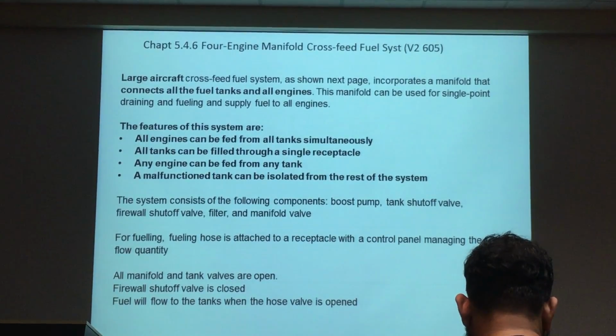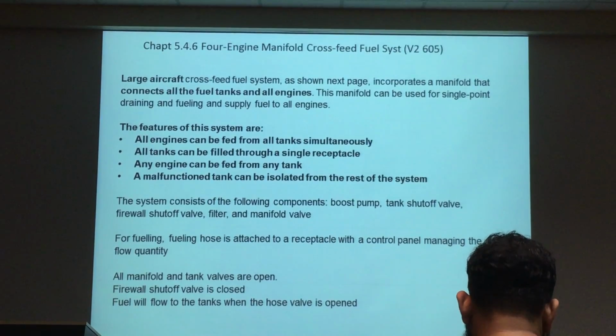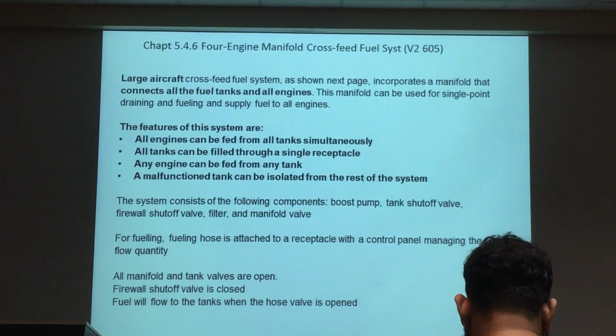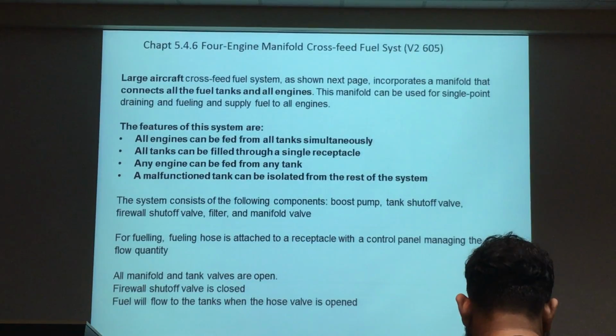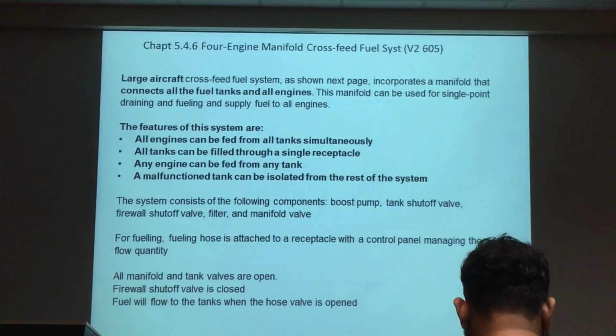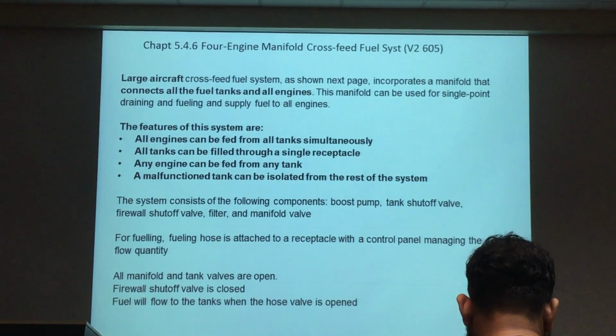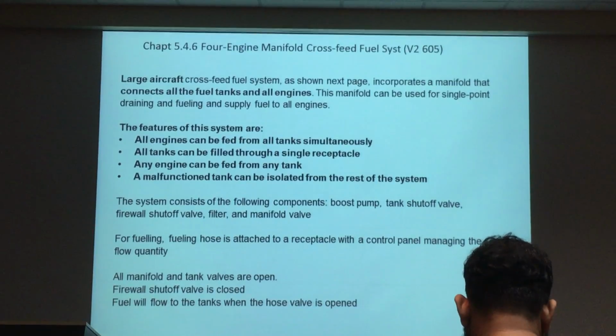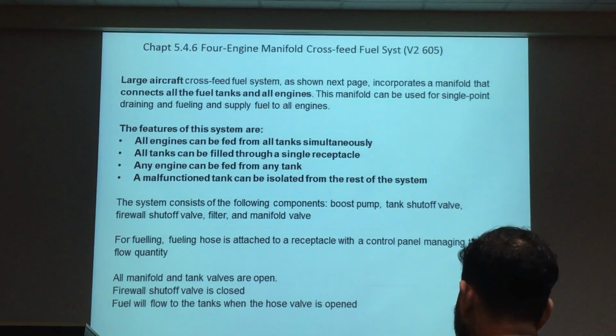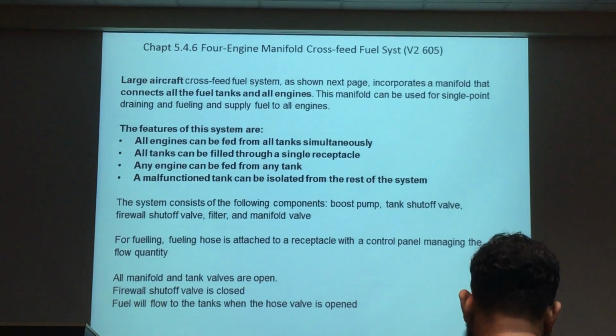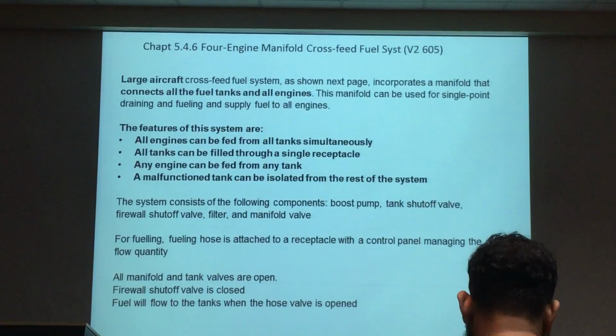Okay, the purpose of the fuel boost pump is to boost, to create a pressure head difference for the fuel to flow to the engine. The purpose is to remove what? Why must you have a positive pressure when it comes to the engine side? Cavitation. Cavitation, okay? On the ground they don't have such a problem because you're under high atmospheric pressure. But in the air, the atmospheric pressure is thinner and thinner. Okay? If you don't have positive feed, you tend to have a cavitation problem. Remember when you open up a soda bottle, a lot of gas comes out. The same thing. You don't have the pressure head to press it.